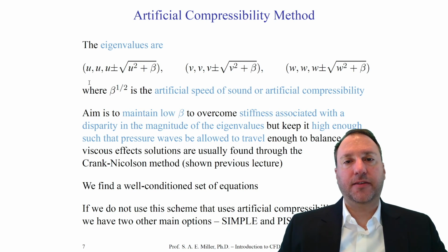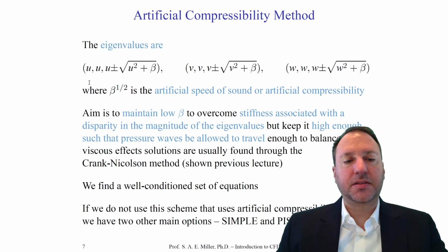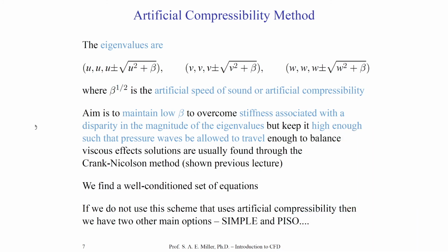So you can see if u is near 0, or perhaps the mean flow velocity for compressible flow, then we'll have some eigenvalues which are very, very close to 0. This is a problem, and it might create a system which is rather stiff, and that is slang in a sense, meaning it's hard to solve with a linear algebra technique or numerical technique in general.